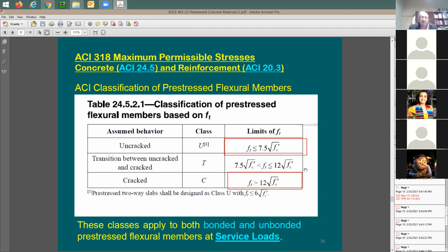How about in between? Yes, go ahead. Sorry, do they coat the cables? Does it coat it? Yeah, the pre-stress cable? Yes, it comes in sleeves, like a hose, like a conduit. You know the electric conduit. And usually it is going to be covered with grease.